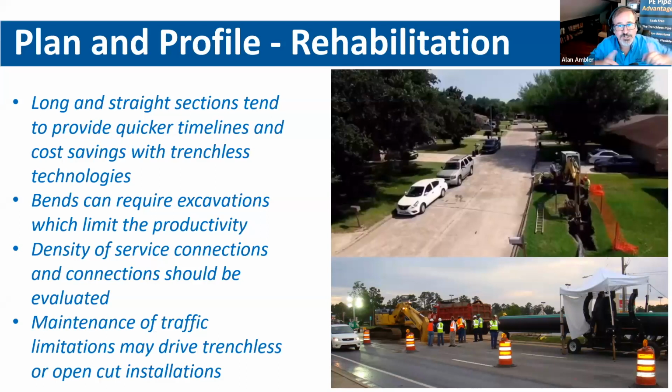But in trenchless application, they'll often add a significant amount of HDPE on either side of it, so we don't pull through that. In a more permanent condition, such as above ground installations, we're looking at some temperature fluctuations, and that's a little more complicated in the assumptions you have to make about the install. And we'd be happy to work with you on some of those specific to above ground as we go through it.